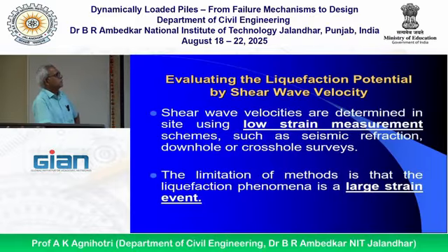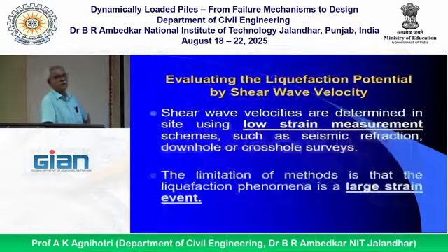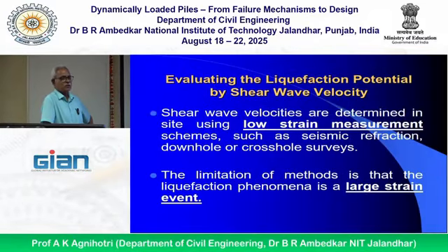Now evaluating the liquefaction potential by shear wave velocity. Another method is by shear wave velocity. Normally we perform standard penetration test or cone penetration test. Sometimes shear wave velocity test is also performed. Shear wave velocities are determined in situ using low strain measurement schemes such as seismic refraction, downhole or cross-hole surveys.